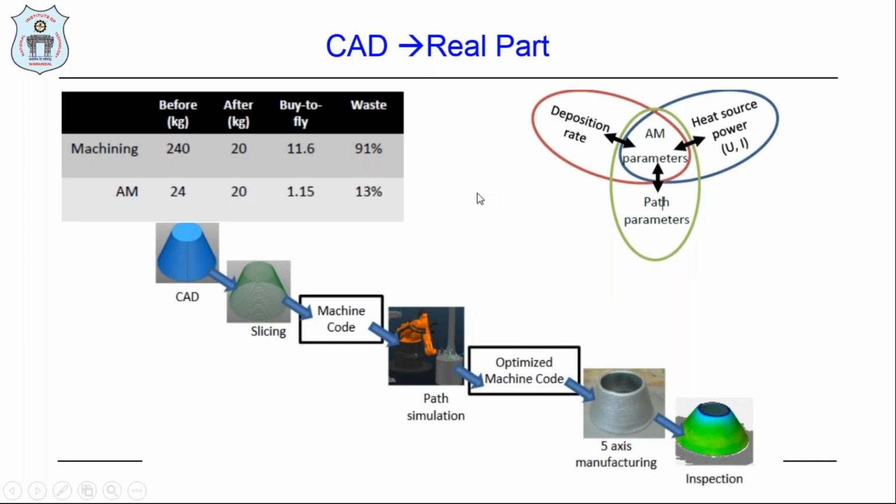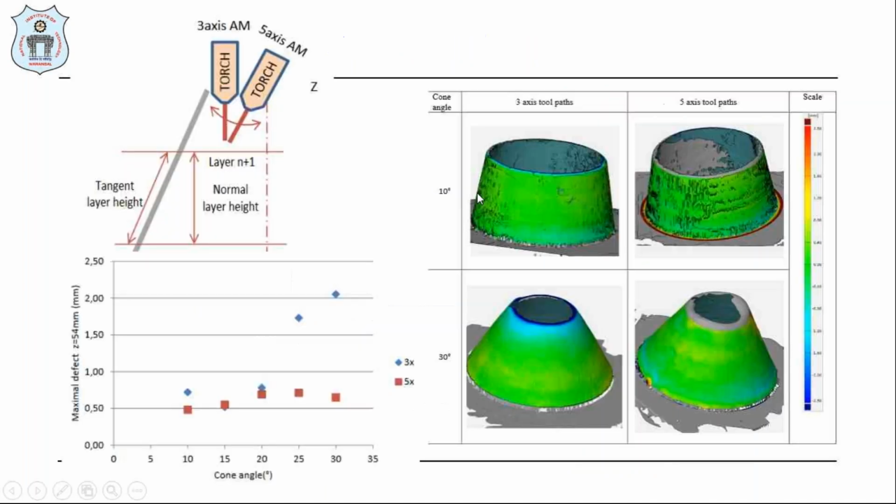You want to build a core structure with the help of different axes, either 3-axis or 5-axis. In 3-axis we are able to build it, but the deformation defects are greater in the 3-axis machine when you compare it with the 5-axis machine in the WAAM process.